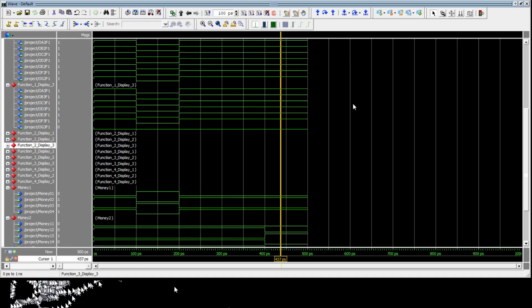The third question, does your design use the minimum number of gates? How many? I think my design uses the minimum number of gates, which is 24 gates: 8 NOT gates, 1 NAND gate, 7 OR gates, which contain 4 two-input OR gates and 3 four-input OR gates, and then 8 AND gates. The fourth question, does your design use the minimum number of chips?